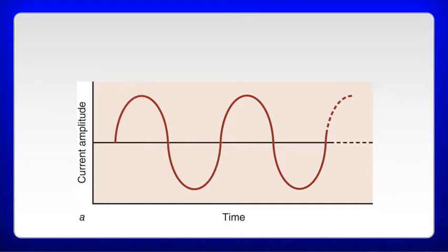As we said, there's an inverse relationship between the phase duration and pulse frequency. Frequency represents the number of pulses per second. Let's say we cut it off here, and that was representative of the frequency of this current. Well, you would have 2 pulses per second because you would have 1, 2. The reason you have an inverse relationship is that as the phase duration gets bigger, you're going to have fewer pulses, because the phases, and this is a phase down here as well, are going to get wider, so you won't have as many pulses per second. If the phase duration was shorter, meaning this was more narrow, you'd have room for more pulses.